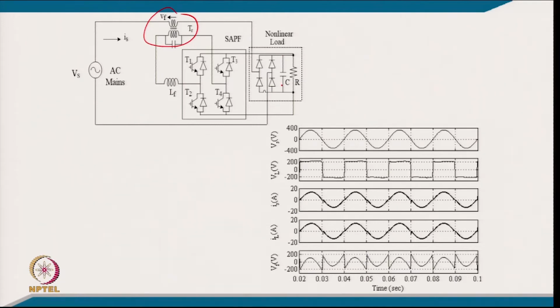So, in this case we can just see it is a supply voltage, and this much is typically the voltage we have to regulate across the load, which is the DC link voltage of the series active filter also, and then we have a sinusoidal supply current as well as the load current, and the difference of this is typically the injected voltage. So, we are injecting the minimum voltage in a manner that the DC link voltage as well as the AC RMS voltage are both the same. So, the AC RMS voltage should be such that we inject the minimum voltage.